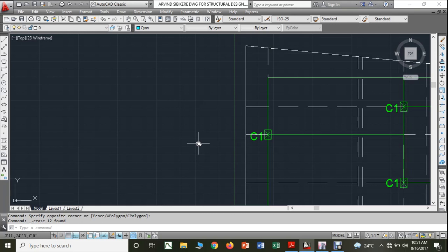See, the plinth beam will receive only the load equal to the weight of the wall. Plinth beam is provided just to make the structure stiff and to have a platform to construct the wall at the ground floor. Therefore, the load received by the plinth beam will be less compared to the roof beam, so we can have a smaller dimension for the plinth beam.